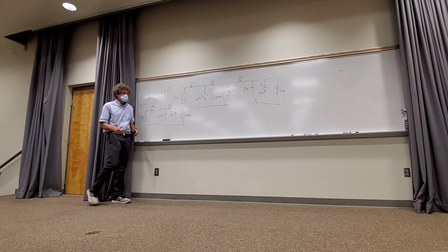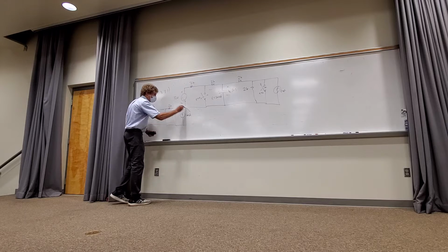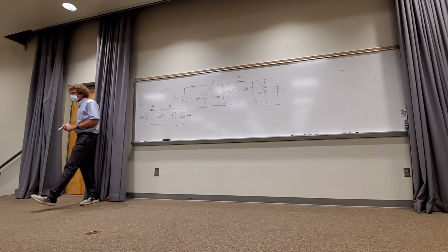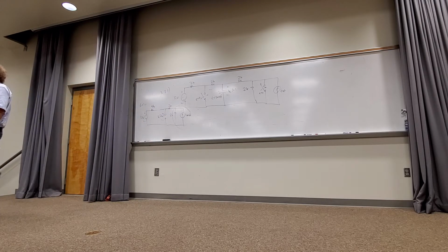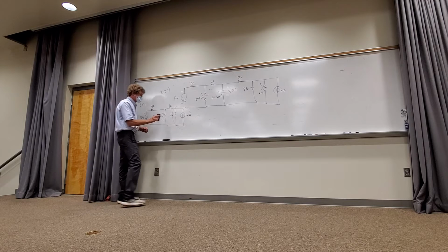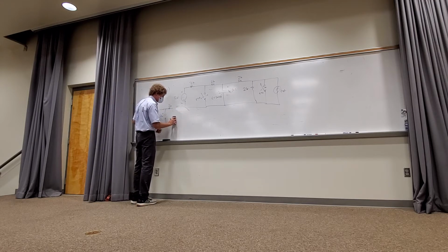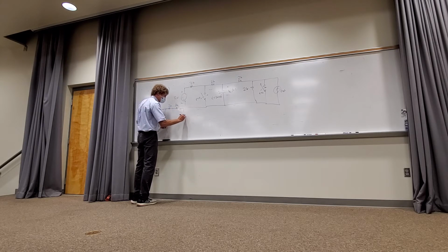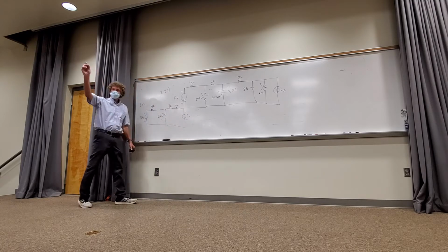Will you repeat that one more time? Sure. Right here, I have 2K ohms in parallel with a 2 milliamp current source. Correct, class? Can't I make an equivalent of 4 volts, 2K times 2 milliamps, in series with 2K? How many see that? All right, so that's what I'm going to do. Is that answering your question?